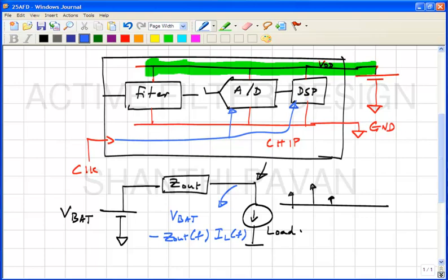But it also has components predominantly at which frequency? At the clock frequency. And why is that? At every clock transition there is stuff happening, right? So there will also be components at the clock frequency and its multiples. Okay.